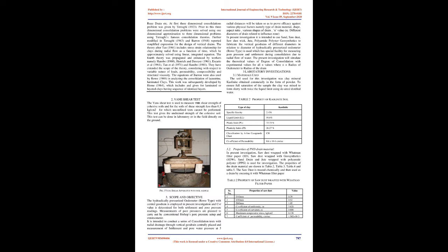Most of the soil deposits have greater permeability in horizontal direction, which can be utilized efficiently by the use of prefabricated vertical drains. After the use of sand drains, several new types of geodrain have come on the horizon, with different shapes and material, namely sandwick drain, jute drain, polypropylene drain, cardboard drain, rope drain, etc.